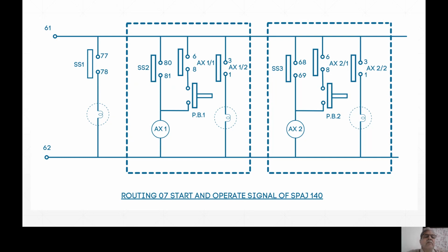So the client will object that I was in America, in the USA, in Canada for the last 10 years. And after 10 years, when I come, I am seeing a bill of some 500 rupees or 1000 rupees or 8000 rupees. How? When I'm not there, why is the bill there? Because the meter is creeping, because the disk is creeping. And therefore, in the energy meters, the anti-creep arrangement has to be provided. I was there for 3 years in an analog energy meter manufacturing factory, so I know everything. Anti-creep arrangement is required so that the meter does not creep.